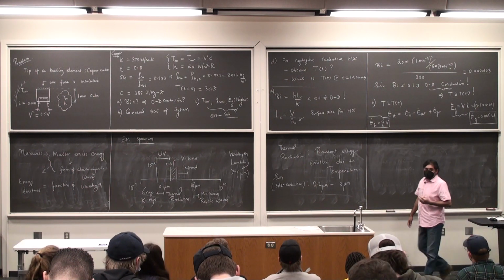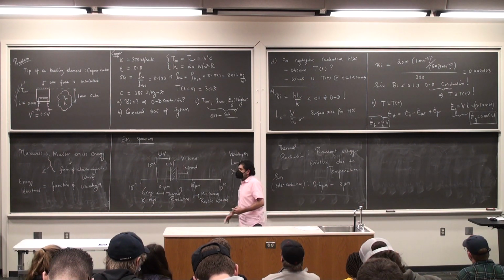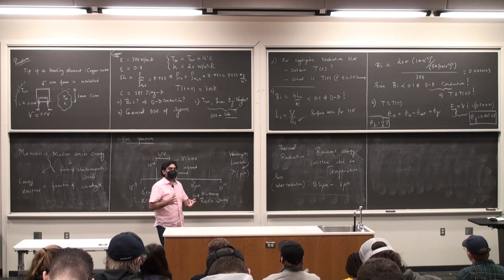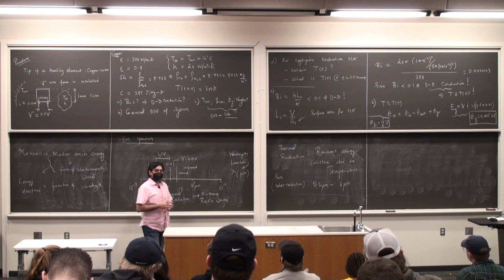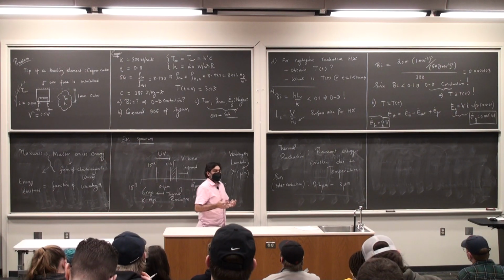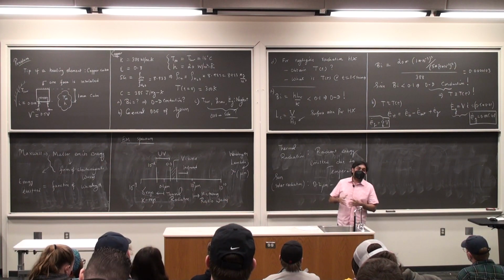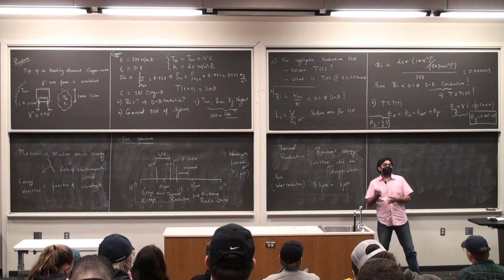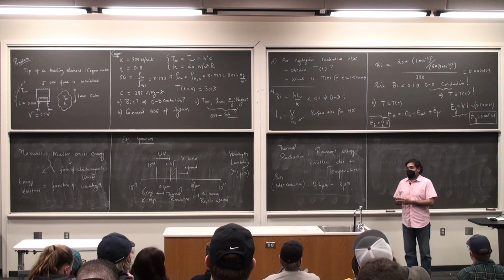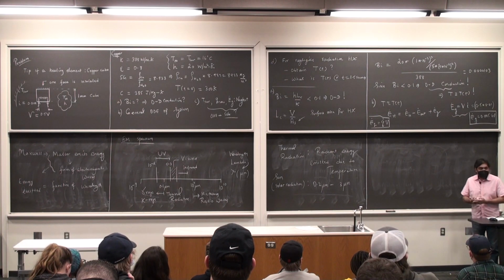And the sun is important in many ways because, of course, it's our major source of light, but it also acts in some way at certain values of the wavelength as an ideal body. And by understanding the sun as an ideal body and by enacting principles of thermal radiation on that ideal body, it is possible for us to experimentally obtain what can happen on a real surface. So that's where our motivation is in looking at solar radiation.